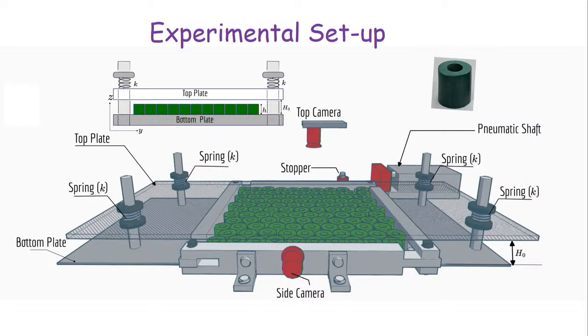It moves, and if there is internal stress developed in my system and those particles want to buckle up, they can buckle up. I'm holding the whole thing up with a top plate, and I have springs on them to just hold them back. So basically I can measure the normal stress acting on it. It gives you a little leeway, but it also allows you to, because if you don't have them, then all the particles will just fly off.